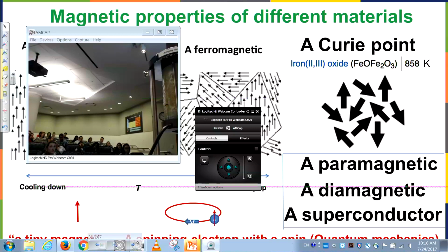But this one, that's why we call it jumping ring. This one again clearly shows the repulsion. So as long as I start inducing magnetic field inside this core, that core induces EMF in this loop. EMF induces electric current. That electric current induces magnetic field, which is opposite, and it jumps.